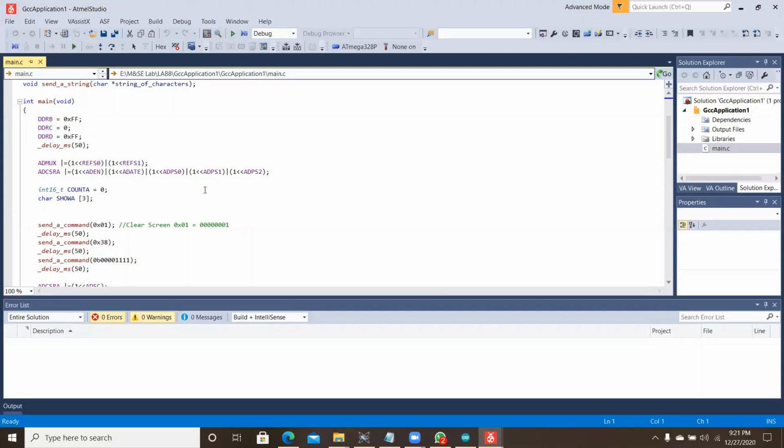where ADC is a register which is used. These conditions are used so that the analog input channel is selected by writing to the MUX bits in ADMUX. Any ADC input pins as well as ground and a fixed voltage reference can be selected as single-ended inputs into the ADC.